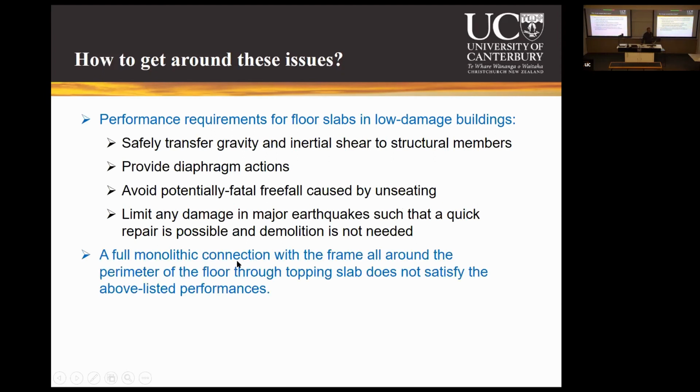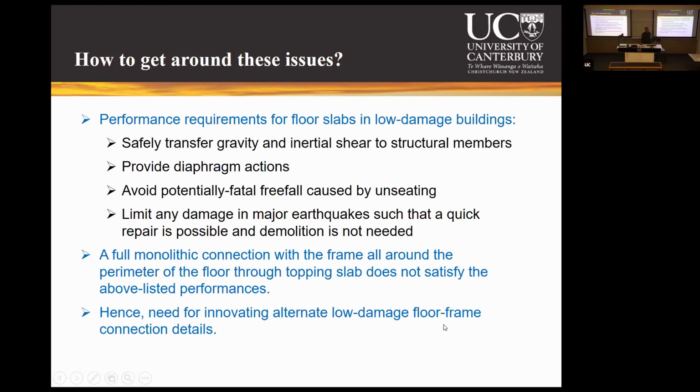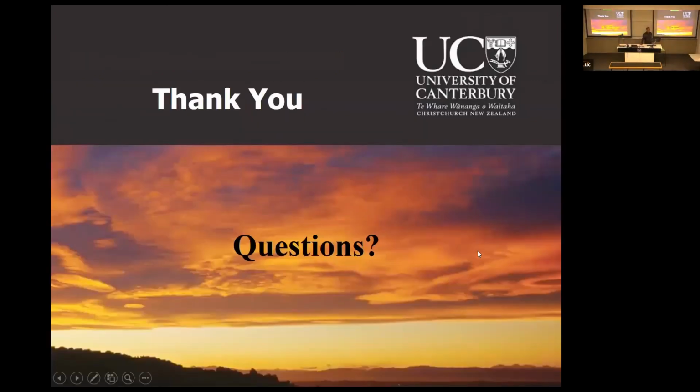So a full monolithic connection with the frame all around the perimeter of the floor through the topping slab does not satisfy all the above listed performance. It might satisfy some, but that's why I say it is not conducive for low damage building design. Hence, we need to innovate alternate low damage floor frame connection details. I think with that, I end my presentation, and I look forward to questions and interactions. Thank you.